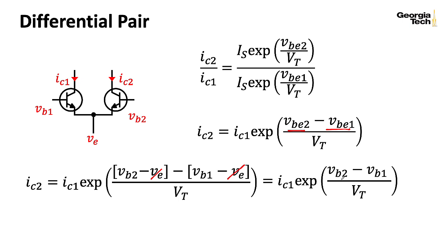What's particular about synthesizers here is the way we're going to use this pair. That's actually a current sink. So for instance, in the sawtooth and triangle wave oscillators we've looked at so far, we've been pulling current out of a capacitor in the feedback loop of an op-amp. Of course, there's other kinds of oscillator designs that have the capacitor just kind of floating and not in the feedback loop of an op-amp. But whatever you're doing, the same idea applies. So this current sink here is connected to the kinds of circuits I've shown you previously in the triangle and sawtooth VCO lectures.